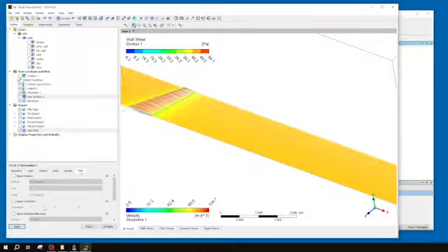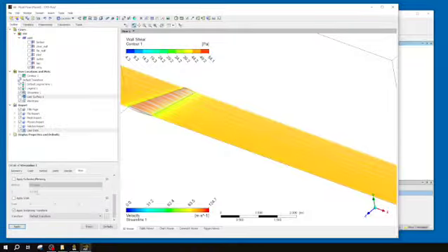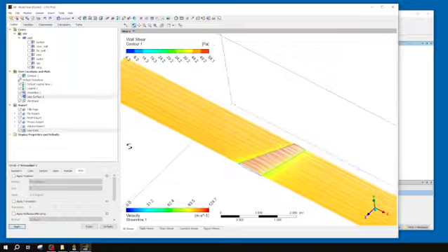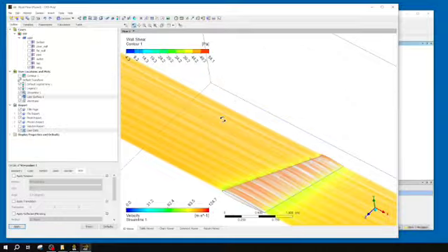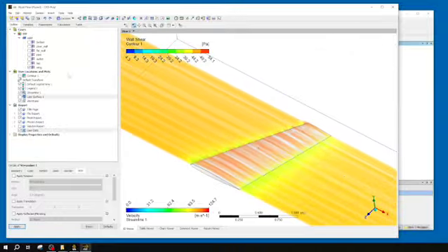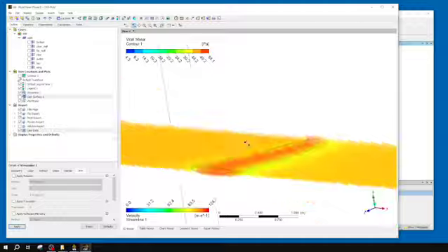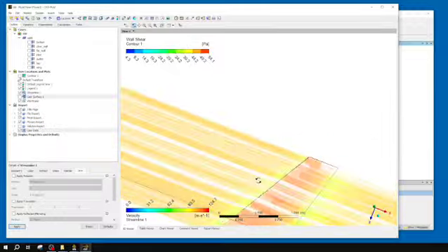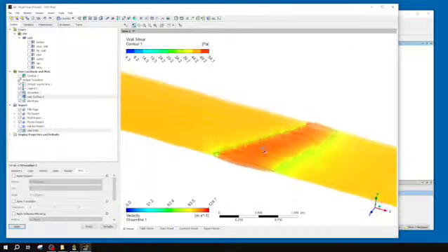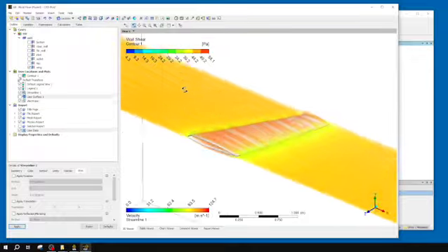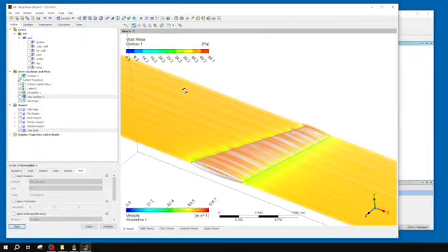Render, same as before and same as view. You can kind of scale it, translate it, whatever you want. But that's more or less the basics of streamlines. Something I will say that I did already do is I made the wing just a white surface. If you don't have that, you can see through the wireframe. So the bottom streamlines get kind of, I confuse them with the top streamlines. So just keep that in mind as you play with different visualizations. It's often useful to leave the surface as solid. But yeah, that's kind of a rundown of streamlines for you.